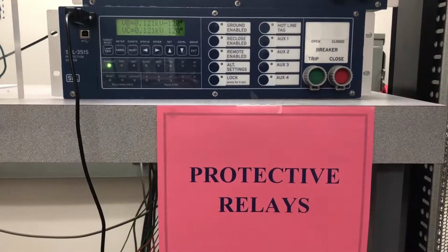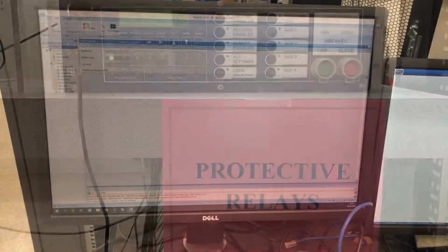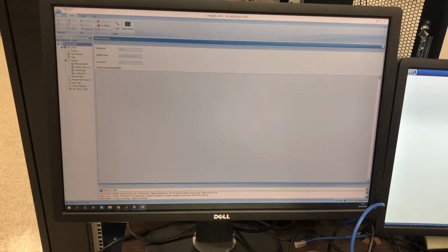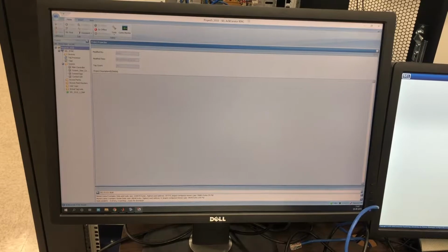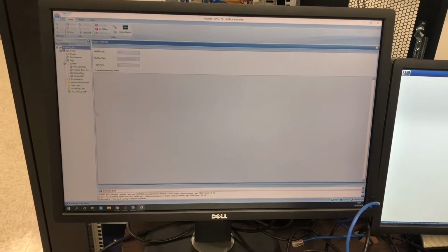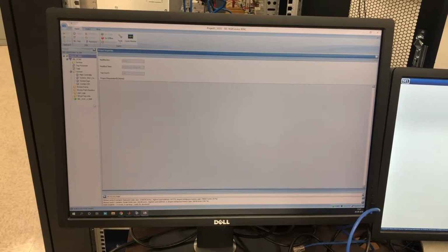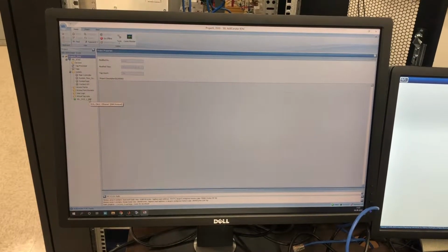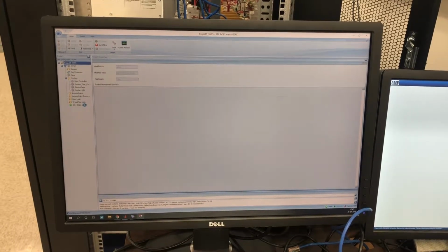Under normal operating conditions, it can be seen that the relay is in its healthy state. The major advantage of using an RTAC is that it is possible to remotely control your protection system using a simple click of a button using the RTAC Accelerator software. So in this example, we will demonstrate how we can provide a trip signal to the 351S relay using this software. All we need to do is go into the SEL 351S, which has been connected via a DNP protocol.